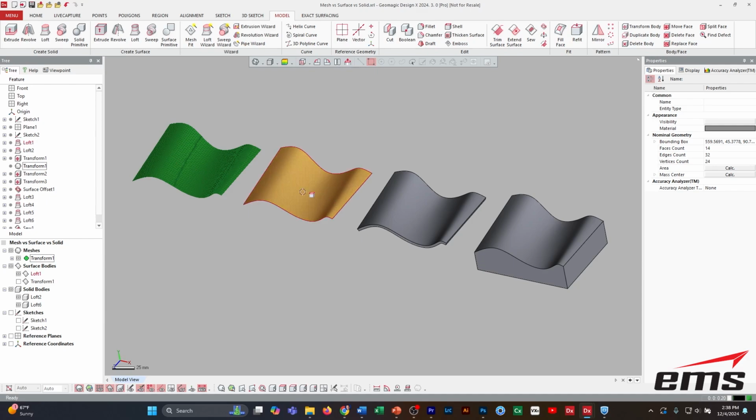Well, once I turn it into a surface or a solid, during that process of creating it, I can make changes, or I can make changes to it down the road. So I'm not going to get into that too much, but generally for any manufacturing process, you have to have a surface or a solid model for CNC machining, for casting, for developing an injection mold, whatever it is. All of those downstream systems require mathematical surfaces or solids.